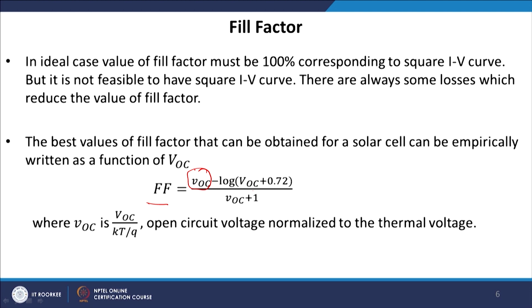With what have we normalized it? We have normalized it with the thermal voltage. And what is the value of the thermal voltage? It is the Boltzmann constant times temperature divided by the charge of an electron. So if we know the value of VOC, the open circuit voltage, then we can calculate the value of the fill factor.